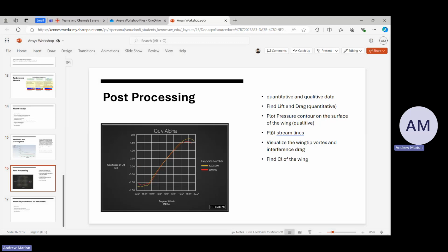Your plane could be going 5 meters per second at this airspeed and these conditions, but that doesn't mean much to someone running slightly different conditions. It's fine for reporting now, but to compare data with other aerodynamic engineers, you'll want to convert everything into non-dimensional numbers, such as Mach number.